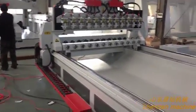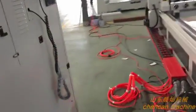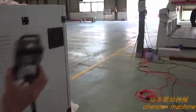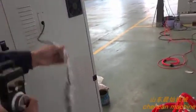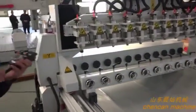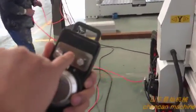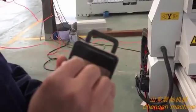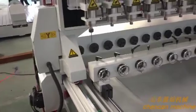The hand wheel is here. We press once, so now the hand wheel will be working. We use this hand wheel. Here we have the X, Y, Z and 4. Also have the 10, 100. Now we turn to X minus and keep going.